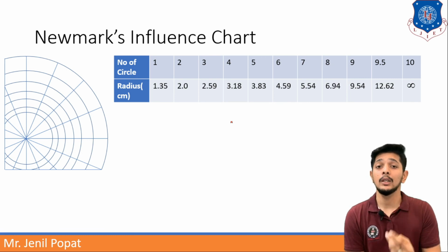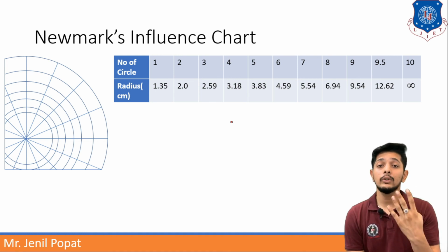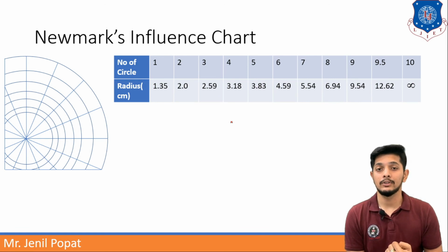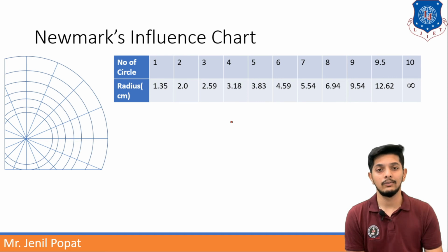The third important point is that you should take care of a change of plan area. If the loading area is changed, you should draw a new plan. And the fourth most important point is that the point P, wherever you are finding stresses, may be within the loading area or outside the loading area, and the method will remain the same. So these are the basic points to be kept in mind when you are using Newmark's influence chart.